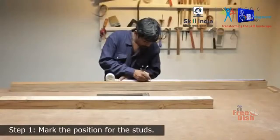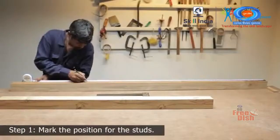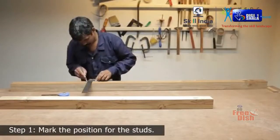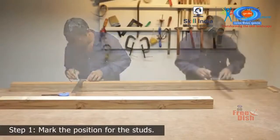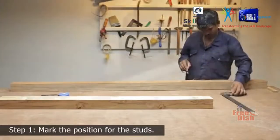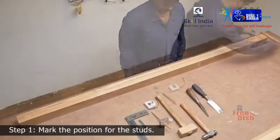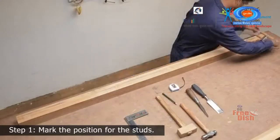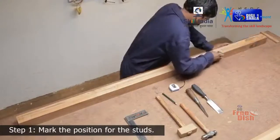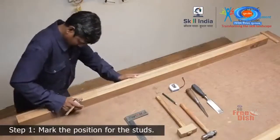Step 1. To begin with, measure the position for each of the studs on the top and bottom rail. Using a try-square and a pencil, mark out all the lines representing the center for the mortise groove for the placement of the studs. In all, you will make 5 such positions for the studs. Now measure and mark the width for the mortise grooves with the mortise gauge on all the 5 positions on both the sides of the top and bottom rails.